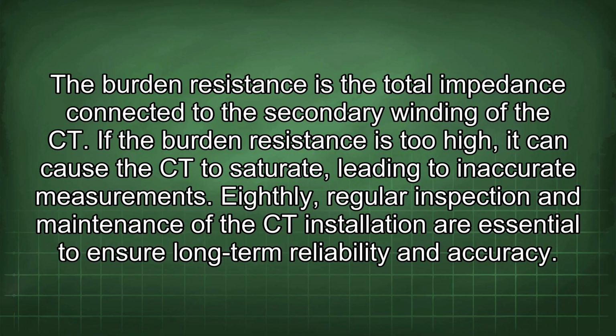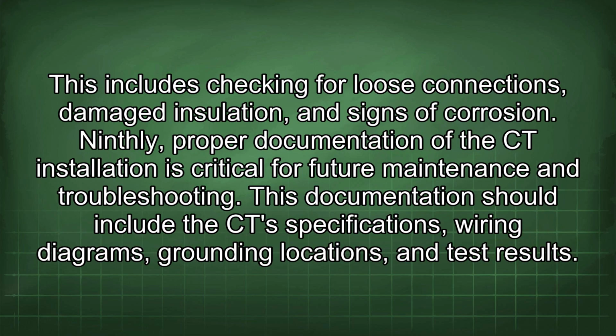Eighthly, regular inspection and maintenance of the CT installation are essential to ensure long-term reliability and accuracy. This includes checking for loose connections, damaged insulation, and signs of corrosion. Ninthly, proper documentation of the CT installation is critical for future maintenance and troubleshooting. This documentation should include the CT specifications, wiring diagrams, grounding locations, and test results.